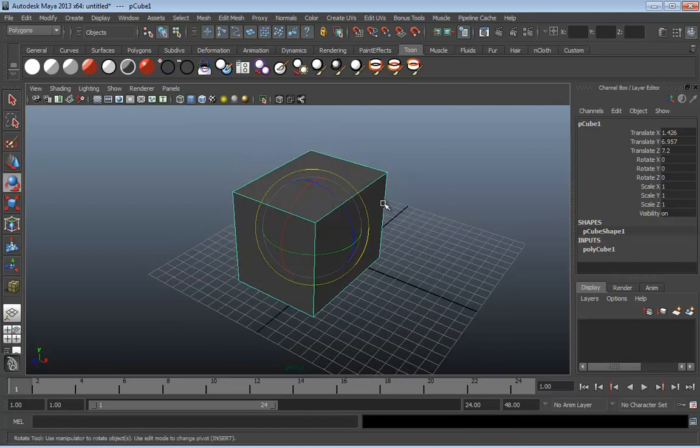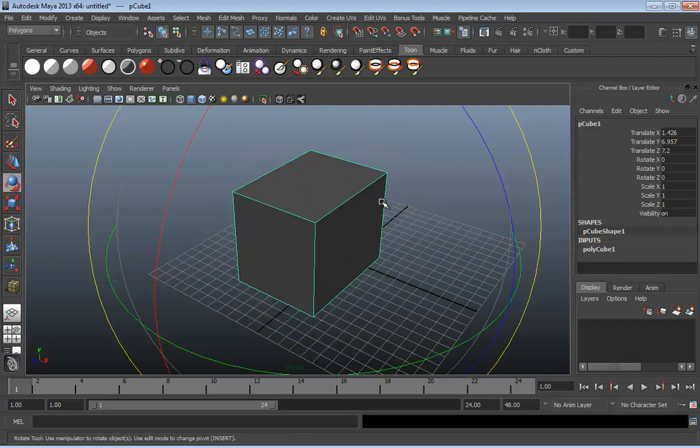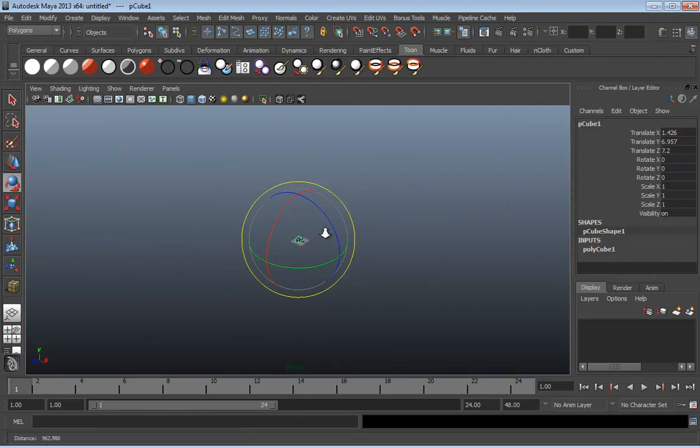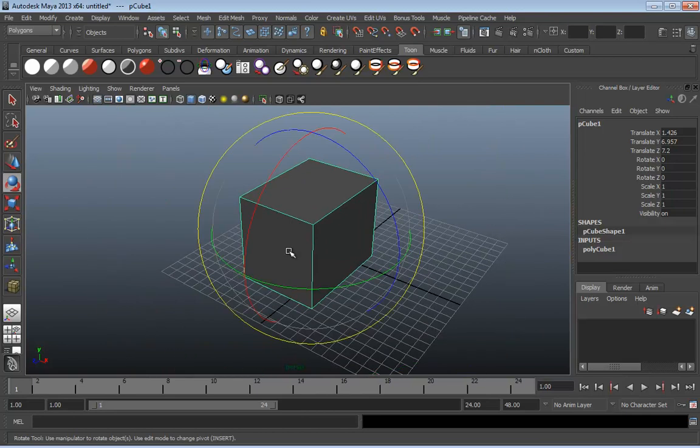Okay, now, one quick thing I did fail to mention about the Move tool, but it's true about the Move tool, the Rotate tool, and the Scale tool. You can press the plus and the minus keys to make those bigger and smaller. Why is that important? I've had people tell me that they seem to have a Move tool and something like a Scale tool, but their Rotate tool is missing. And it actually took me a little bit of back and forth to discover what they had done is they had made their tool so big it wouldn't fit on the screen anymore. Because this tool gets bigger as you zoom in and out. So if you just make it huge, no matter what your zoom level, you won't be able to see it anyway. So definitely remember your plus and minus keys. It will save you some hassle.